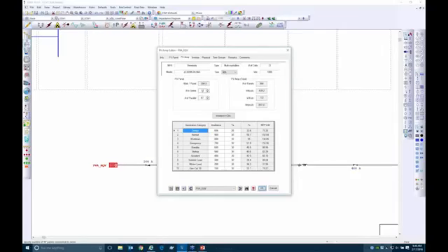So it's like putting 12 AAA batteries together and making a larger voltage battery, so that we're essentially putting 12 of these in series and 47 of them in parallel to give us a total kilowatt DC of about 172 and a total DC voltage of about 440, as I mentioned earlier, about 564 panels and about 400 amps DC that we expect from all these panels going into the inverter.